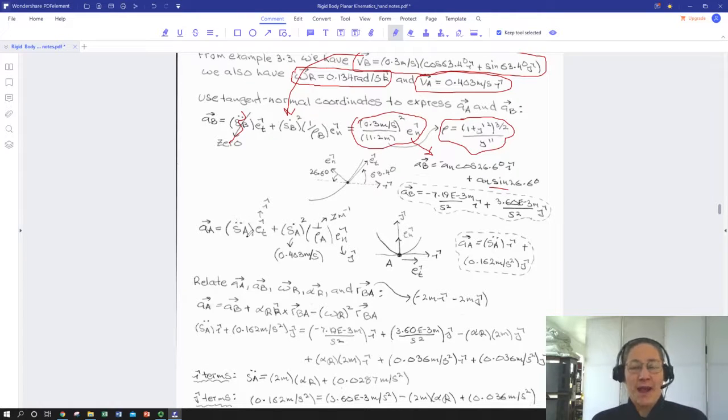So we've got whatever the tangential acceleration happens to be for point A, pointing in the tangent direction, which is also the i-hat direction. And then we have its velocity at that point, which we solved in our previous problem, and we also have a numerical value for our radius of curvature. So we have an expression for acceleration of point A with only one unknown. We don't know the tangential acceleration, which is also the i-hat acceleration.